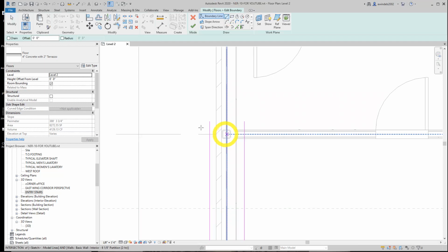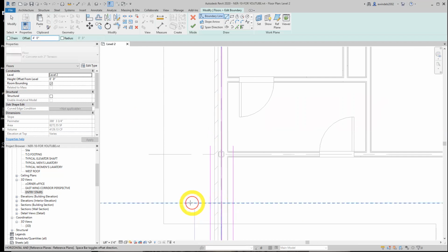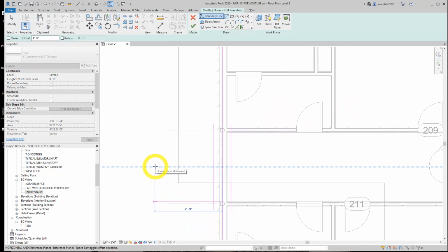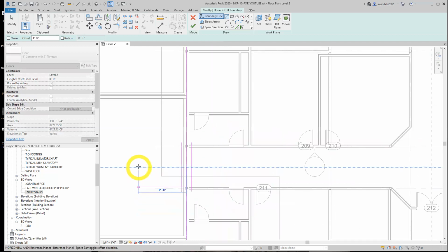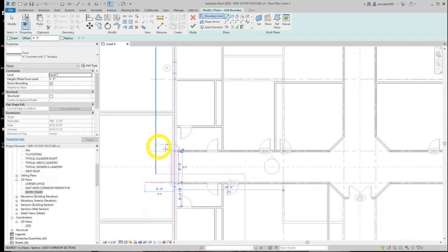Centering on the reference plane. So we could do this. Let's say 4 feet about the reference plane, just so we can be exact. Yeah, let's do that. So I don't pick in the wrong spot on the column. So I put my offset. I have the regular line command here, and I pick offset of 4, hovered around the middle of my building, the reference plane right here. So let's say 8 feet, okay? We'll check that later. Let's do the same up here.